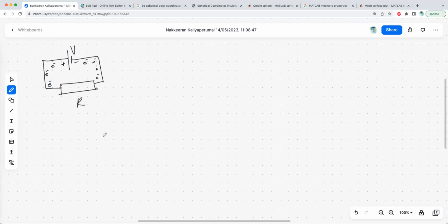It has a potential difference because the charges inside the battery have been separated as a positive electrode and negative electrode. Yes, it has a charge of Q value. But when you have a positive charge or a negative charge separated, what is that going to do with the free electrons available to move around in the conductor? The positive will attract the electrons because the electrons are free to move in the conductor, and the negative will repel them. So there will be an electron movement in this direction.